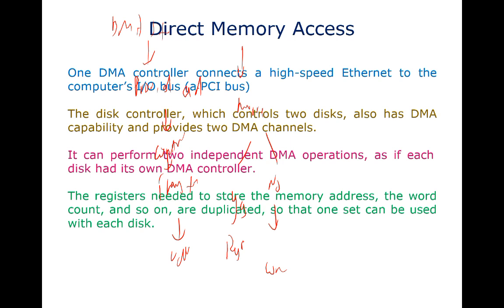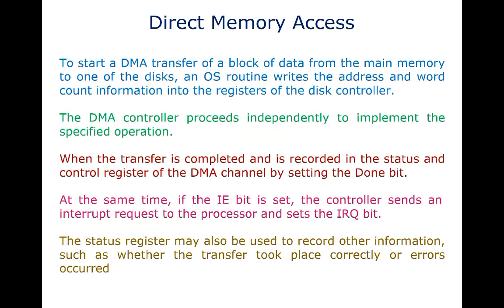After that, the DMA controller will, with respect to this address, count and direction, transfer a block from the IO to memory. From there, it will access the main memory. After that, the DMA completes. Now the interrupt signal appears and goes to the CPU.